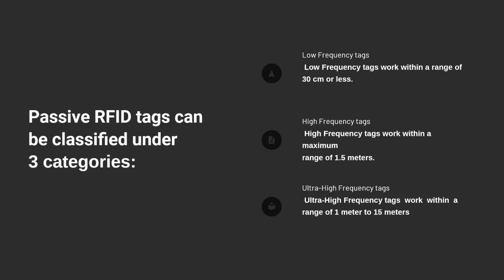Then comes the third category, which is ultra high frequency tags. Ultra high frequency tags is a short, high energy wavelength of about 1 meter, which translates to a long read range. Passive UHF tags can be read from an average distance of 5 to 6 meters, but larger UHF tags can achieve up to 15 plus meters of read range in ideal conditions. This frequency is typically used with race timing, IT asset tracking, file tracking, and laundry management, as all these applications typically need more than a half meter of read range.